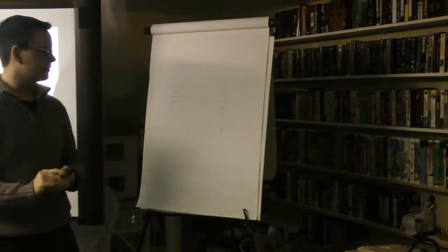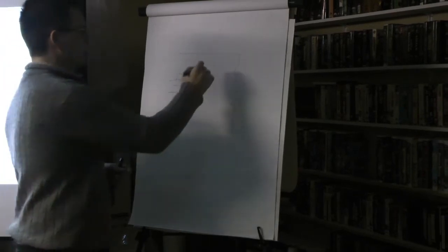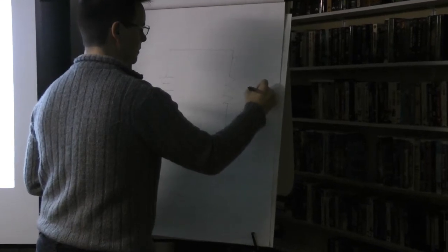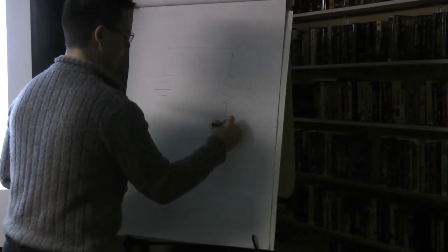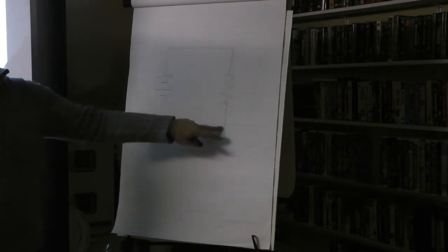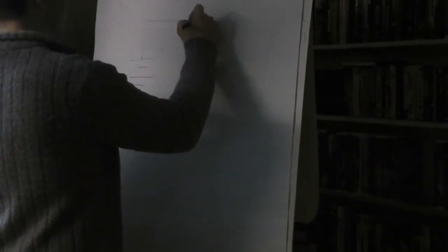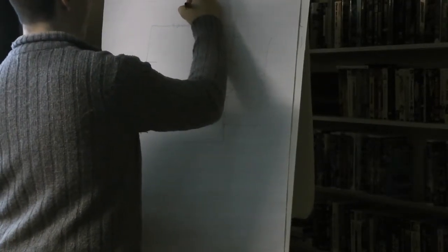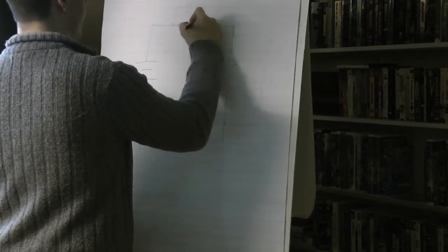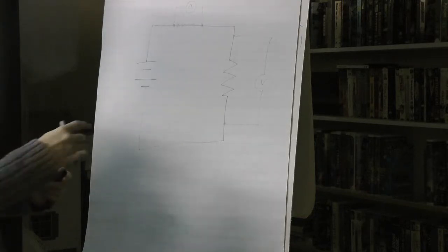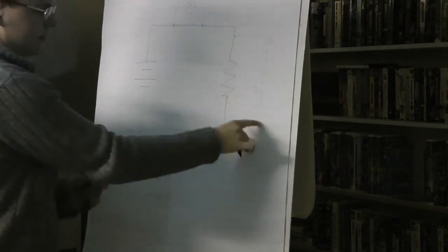So if you imagine you want to find the voltage, right? The voltage is developed across different devices. So you can, let's say for example, connect from here to our voltage meter. And that'll tell us what the voltage is across that particular resistor, right? But if we want to check out what the current is in the circuit, the current is consistent across the circuit. So what we actually have to do is separate the circuit, and splice into the circuit to find out what the current is going through it, right? So that's why this is in series, whereas this is in parallel. Okay.